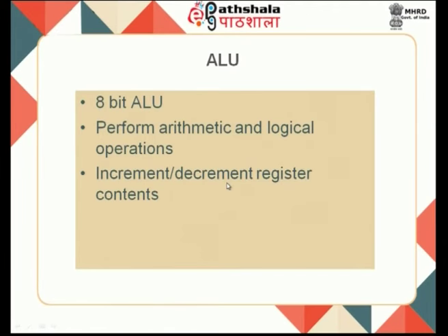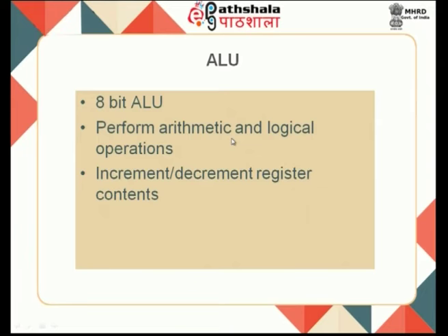And this will be going towards your outputs. Now when I am looking at increment and decrement, not only arithmetic, we will be looking at logical operations also. Logical in the sense I will be doing AND, OR, NOT, all those operations can be performed through your arithmetic logical unit. This takes care of your operand processing and the results will be sent out. Other than that, incrementing and decrementing the register contents is also done by your arithmetic and logical unit. Sometimes the PC value gets incremented, sometimes whatever data is available in your register gets decremented. This also can be done through your ALU.